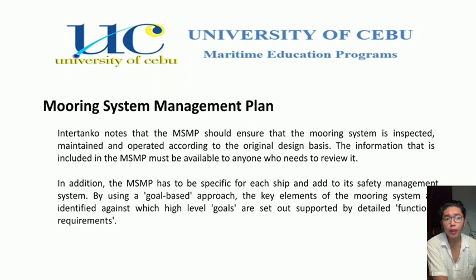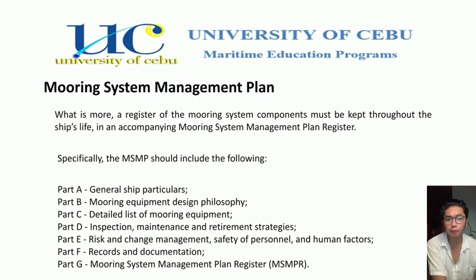In addition, the MSMP has to be specific for each ship and added to its safety management system. By using a goal-based approach, the key elements of the mooring system are identified, against which high-level goals are set out, supported by detailed functional requirements.